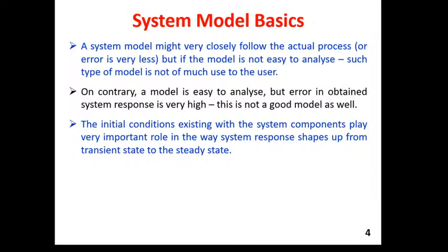The third one is a further more important concern: the initial conditions existing with the system components play a very important role in the way the response is going to shape up. If a capacitor is already holding some charge from the beginning, and then we try to charge the capacitor by some new forcing function, the response will be totally different. The voltage stored in the capacitor after a certain time will be totally different than for a capacitor without any initial condition.